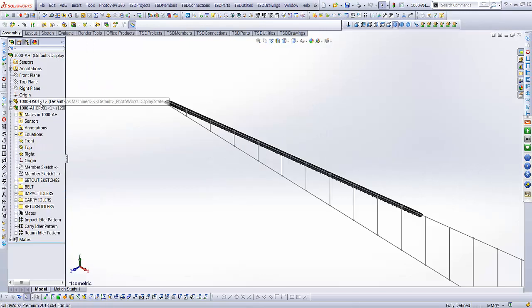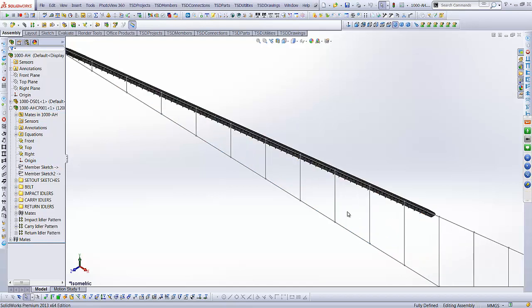So it has its own driving sketch inside it, and inside of it we have a conveyor that we've got as a member, and in the member you'll notice it has two member sketches to attach to the driving sketch. There's obviously a horizontal and a diagonal that we've used, similar to the stairs. Now inside this there are driving sketches that are also being used, so in your weldment members you can create driving sketches and use those as well to attach other things to.